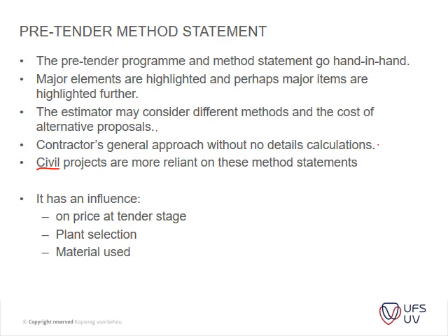Whereas in your civil drawings, you may have a drawing of a building, and the contractor has to, it's measured as one item, a pump house, for instance. So the contractor will have to write a whole method statement to enable him to actually price it. Whereas in the standard system, we measure it out. We've got the strip foundation. The QS actually does the method statement for the contractor, in a sense. So just take note of it, that there is a difference between buildings and civil work.